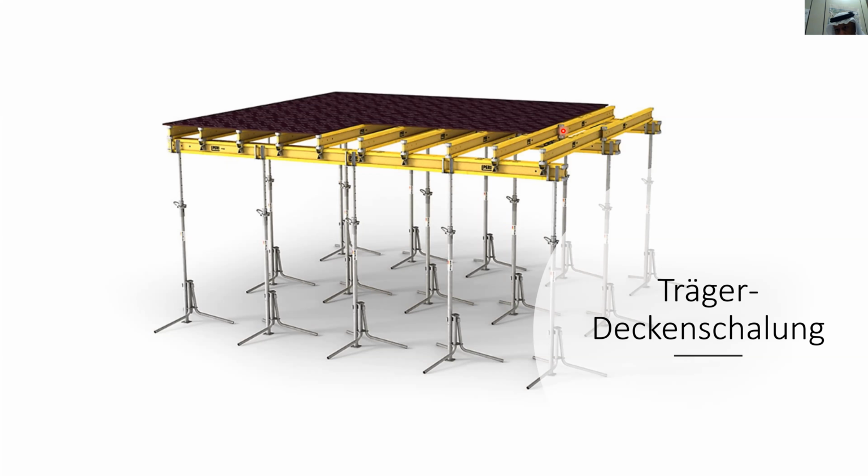So in order to have the correct dimension for the specific weight of the concrete, the distance between the main girders and the secondary girders can be adjusted as well. So you have to think about the thickness of the concrete slab, and then according to this, you choose the supports, the length between the support columns, and the distance between the main girders.